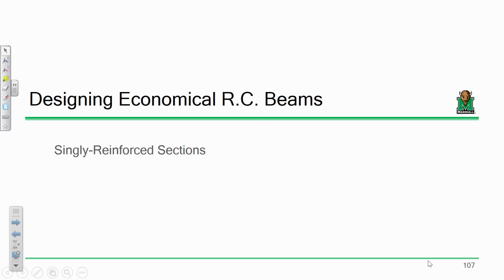I will go ahead and tell you that rho values are small. So when we compute rho values in reinforced concrete design, you don't get rho values of like 6. They come out as like 0.0016 or 0.0027. They're small numbers, so be aware of that.